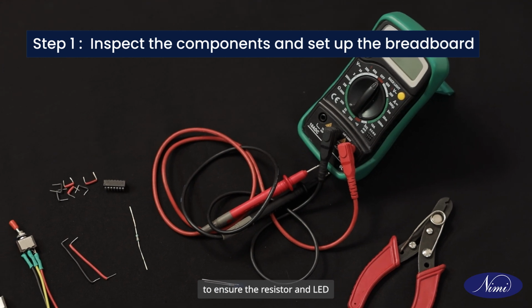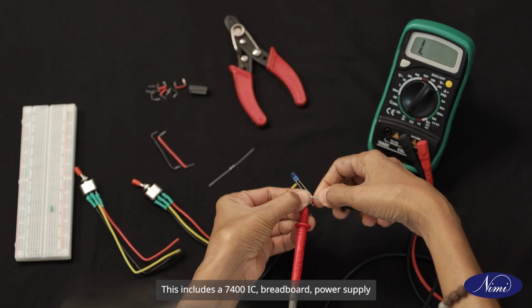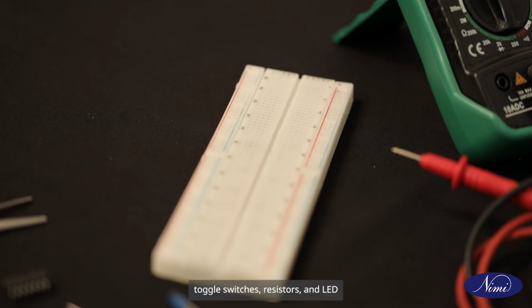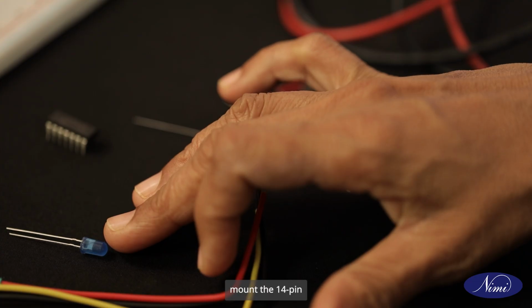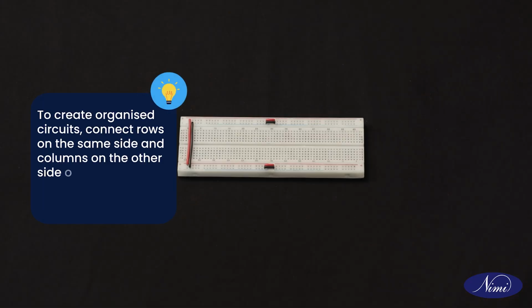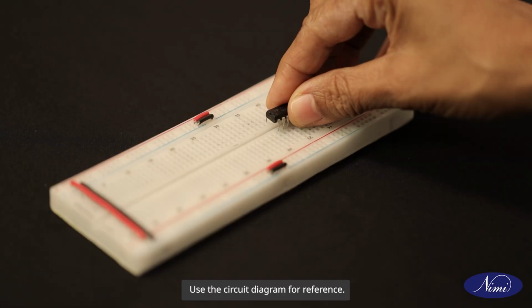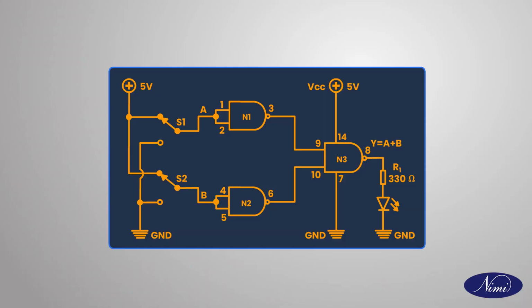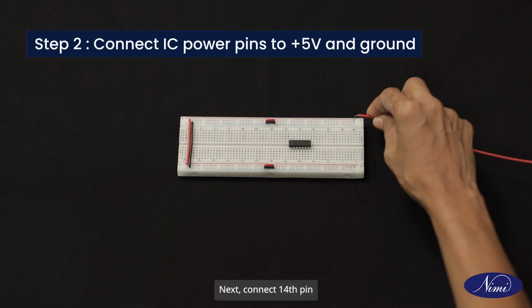Collect all the required components and check them to ensure the resistor and LED are in a working condition using a multimeter. This includes a 7400 IC, breadboard, power supply, toggle switches, resistors, and LED. Once you've got everything, mount the 14-pin IC firmly on the breadboard. Use the circuit diagram for reference. Connect linking wires from the power supply to the breadboard.